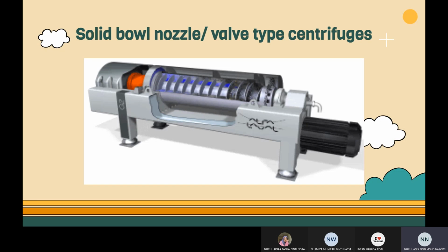It consists of a rotating cylindrical bowl. These centrifuges are a modified disc bowl centrifuge with a double conical bowl and enable the discharge of solids automatically. This type of centrifuge is used to treat oils, juices, beer, and starches, and to recover yeast cells.